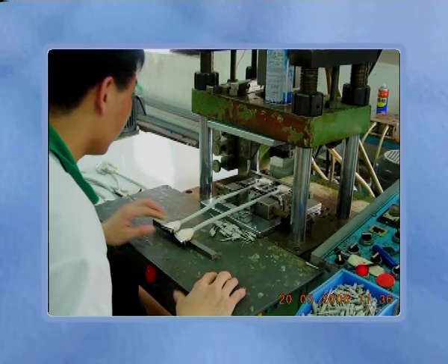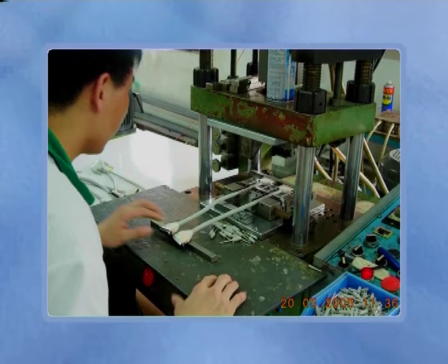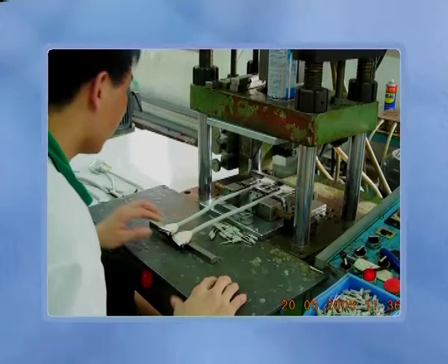The first step is to create a metal plate out of the negative of our initial image through an exposition process, followed by an acid bath. This metal plate in relief is then used in the second step to create the mold, which could be in bakelite board or even glass or plastic, through a first molding process. Once cooled, this master mold will press the rubber or plastic compound through a second molding process to create the printing plate.